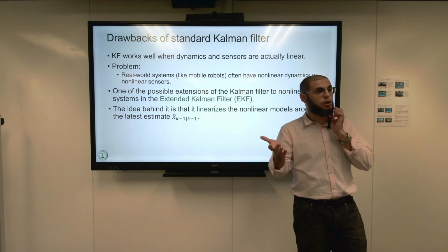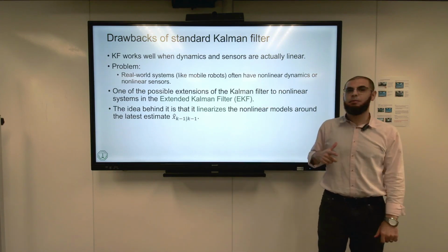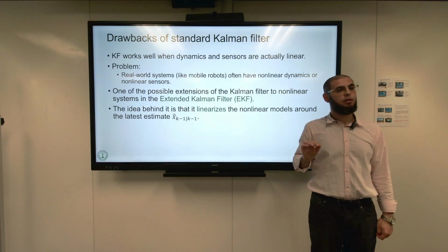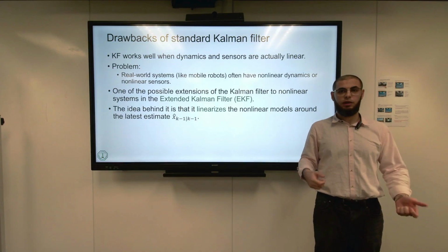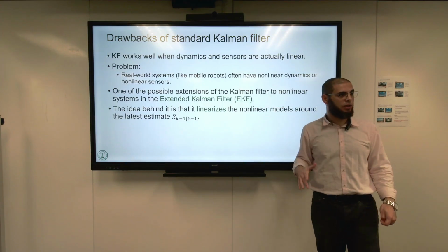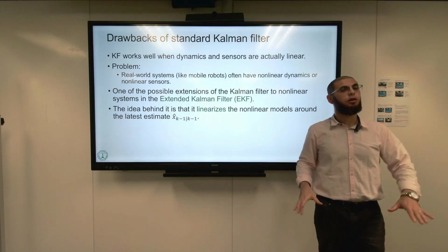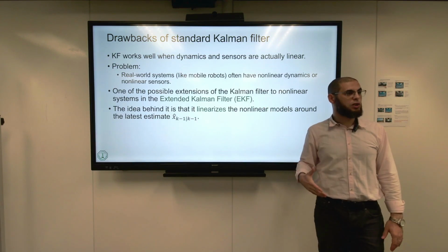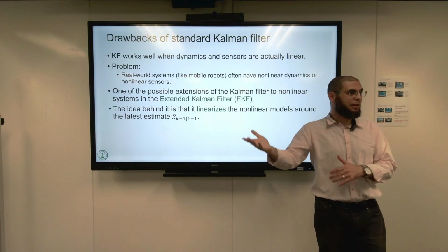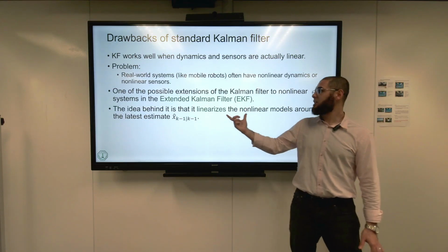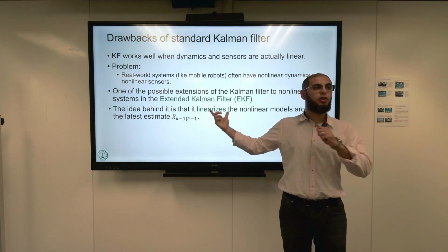One of them, which is the most popular one, is called the extended Kalman filter. The extended Kalman filter as an idea is very simple, and as a performance is actually very powerful. And that's why people love it a lot and they use it really extensively. Even though it has some limitations of its own, it's still much more usable and much more powerful than the Kalman filter. And the whole idea simply is that it does something called linearization of the nonlinearities.